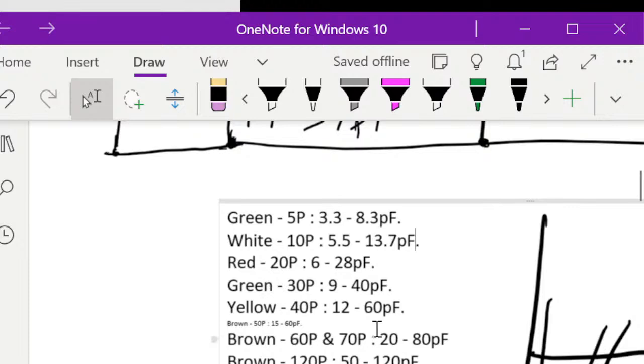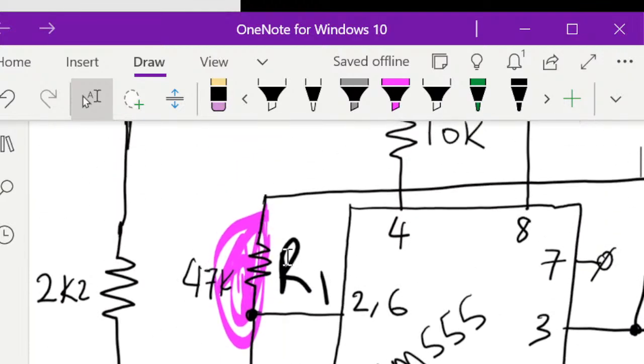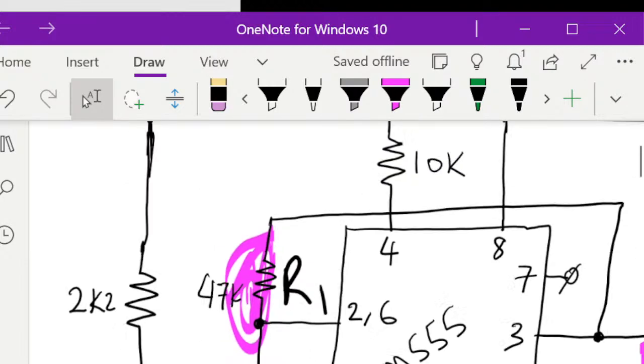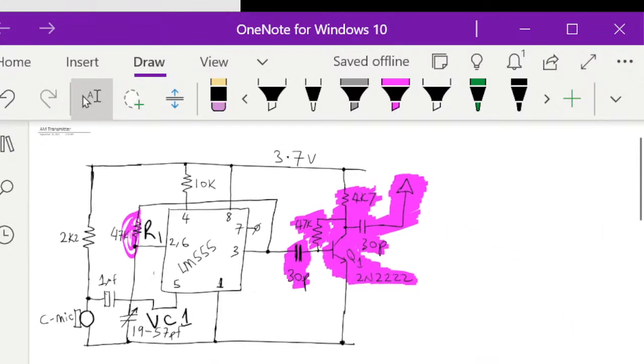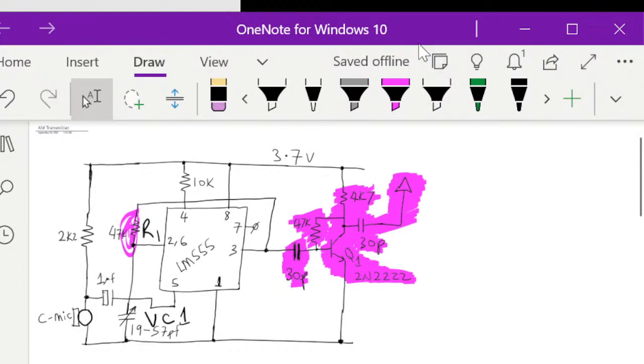We picked one value at random. In our case, we chose the resistor, and then we calculated the value of the capacitor because we have all the values. We have all the mixed values of capacitors, and we chose one that works well for us. So do the same, pick one and calculate the other. The values for this biasing capacitor and resistor for the condenser mic are also based on what we have. And we've used 2K2 several times to bias the condenser microphone, so we just used it again. So experiment and find something that works for you.